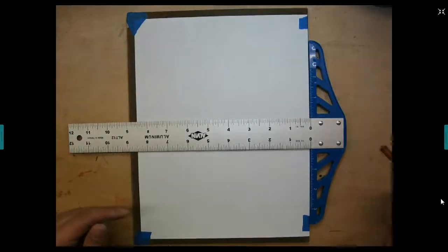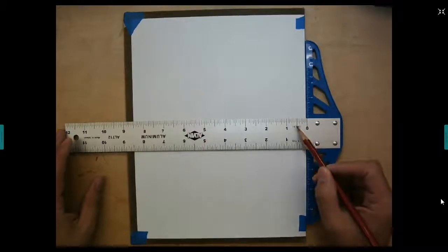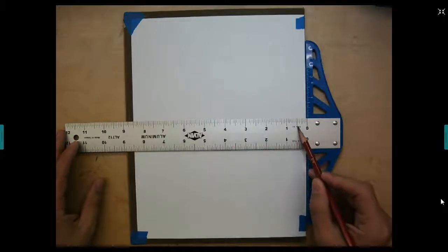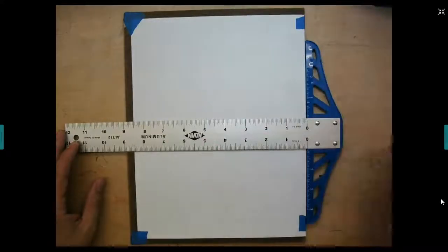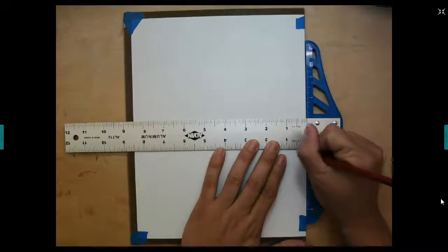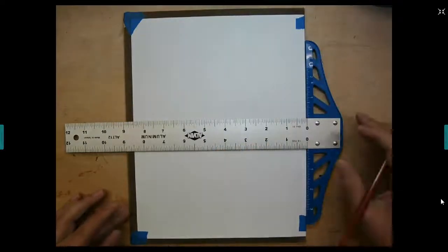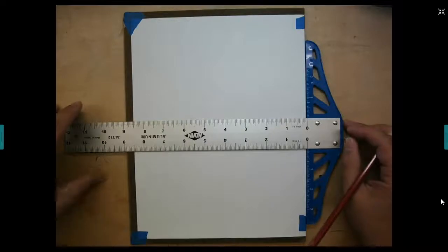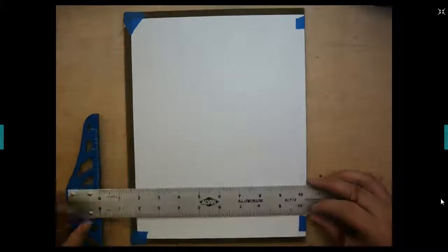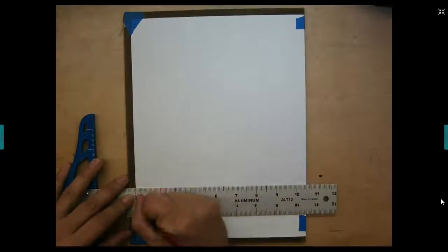I'm going to start with a 1/2 inch border. So for a 1/2 inch border, on a regular bench ruler, you're going to notice these graduations. So I'm going to go 1/2 inch all around. Okay? Now, I know this is being drawn by hand. I don't expect this to be perfectly drawn square. Plus or minus a 16th, a 32nd, that's fine. Just try to make sure it looks right, and square to the best of your ability.